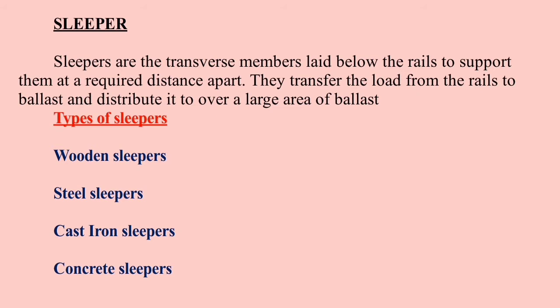What is a wooden or timber sleeper? These sleepers satisfy all the requirements and are suitable for track circuiting. Teak is the best wood for sleepering purposes, but due to its heavy cost, it is used only in girder bridges. In India, sal wood is commonly used as a sleeper. Normally, the life of a timber sleeper may be taken as about 12 years. Their scrap value is almost nil